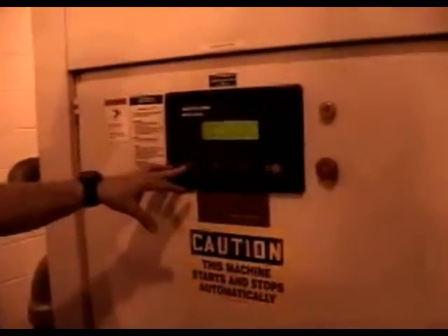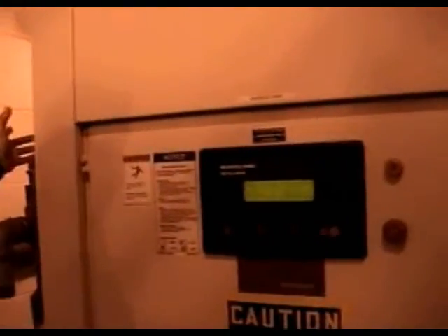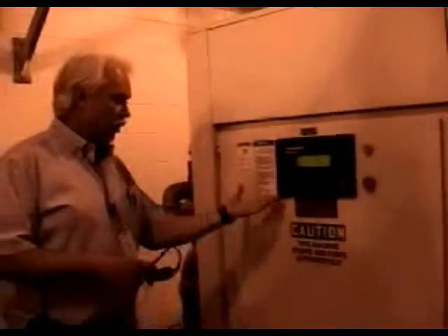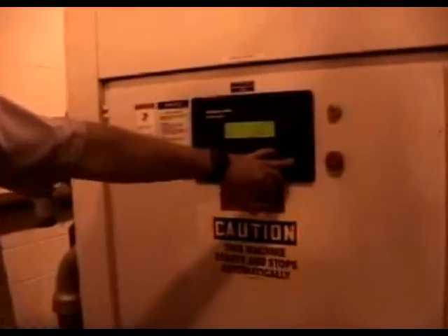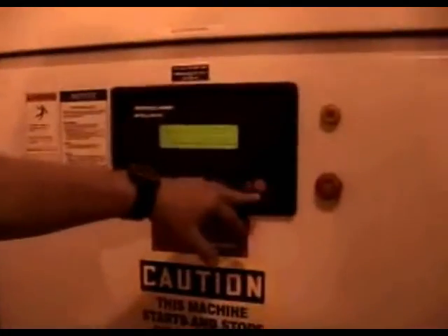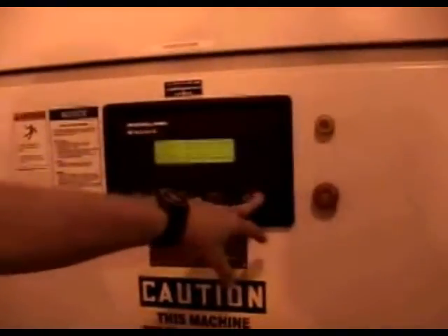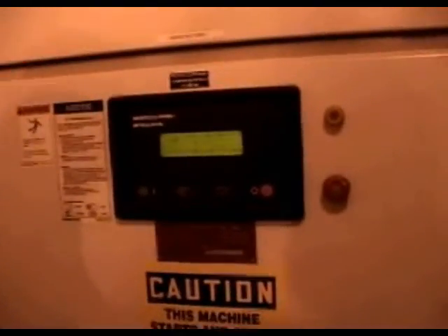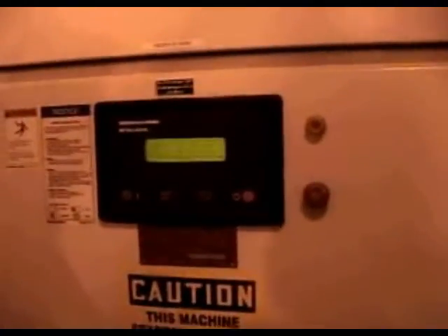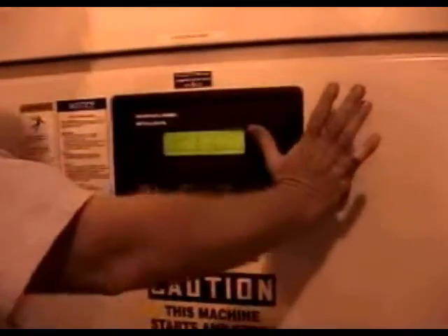If you start a blower up and this air compressor isn't running, the pneumatic valves up on the aeration basin won't open. The blower will still run, but you won't be pumping any air out there. Also, you won't have the ability to run the filters either. To stop it, it's just this button right here. It's a very simple unit to run. That would stop it. If you came in here for some reason and it was smoking or vibration or something like that, this is an e-stop.